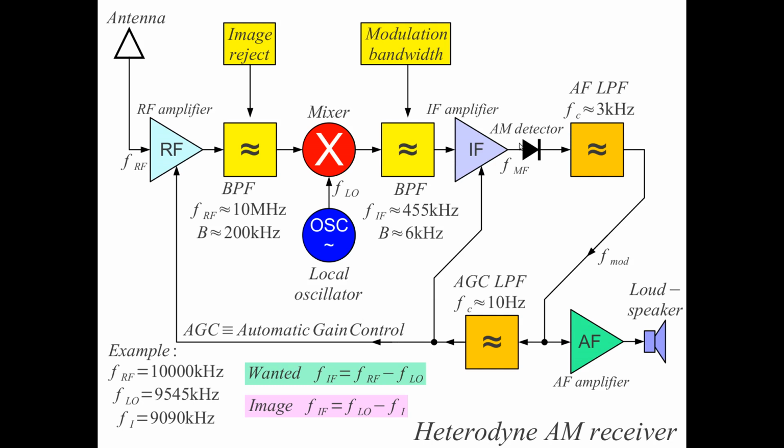So automatic gain control in the receiver, or automatic level control in the transmitter. These are also control loops that are not really required in theory, but in practice they are very handy, because we may receive stations with different power, different signal intensity.